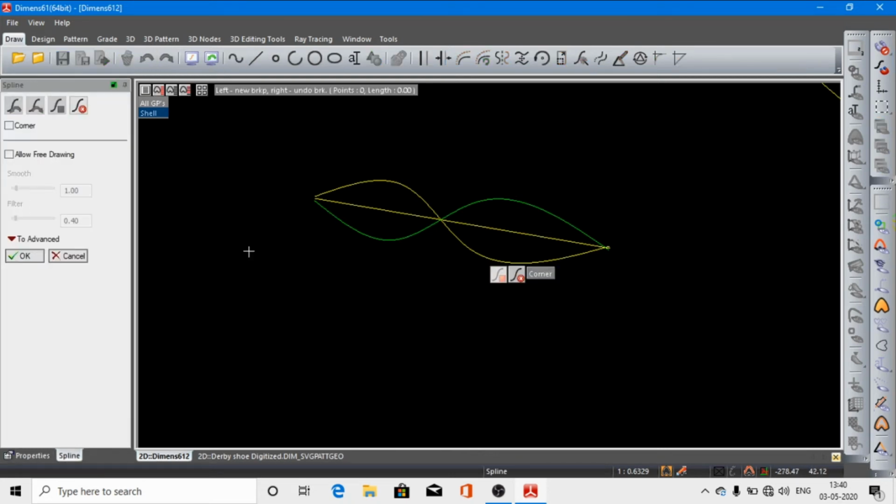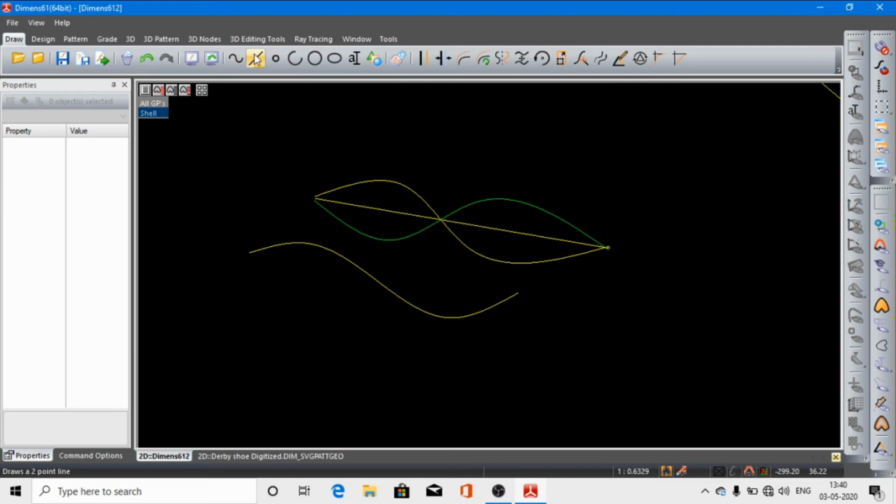Suppose you want to mirror any shapes, like this shape. If you want to finish your line, you go to this icon. You can watch the cursor carefully and left click there. And then you have to draw another axis line. Okay, you go to draw one axis line.